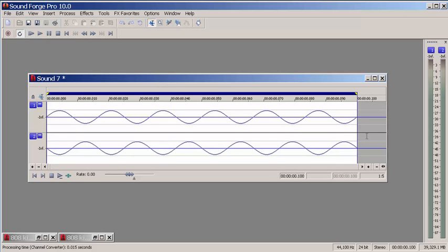This teaches us something important now. If you have what we call partial phase cancellation, i.e. maybe it's at 90 degrees out of phase, or 45 degrees, or any value, what will happen is some frequencies will cancel out. Some will get summed with their amplitudes. This is why I showed you what happens when you sum earlier. In other words, parts of your audio signal will sound hollow because they'll be empty. Others will sound really grainy or metallic. Others will sound really loud and distorted or just loud. You get a lot of different anomalies.